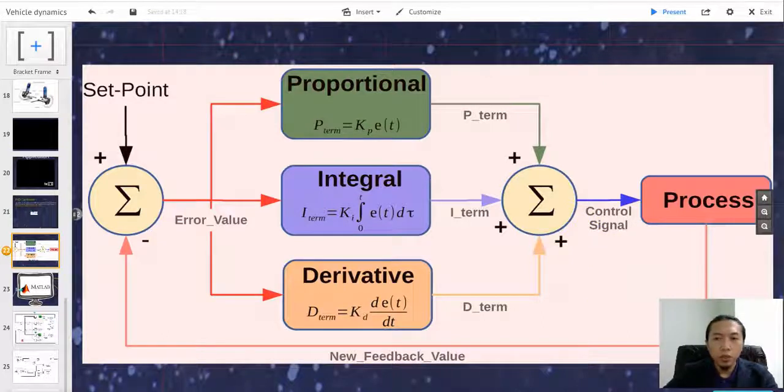So the desired closed loop dynamics of the process can be obtained by adjusting the three parameters Kp, Ki, and also Kd. So inside the lab session, we have the values for P, I, and D. These values are often iteratively tuned, without specific knowledge of a plant model.